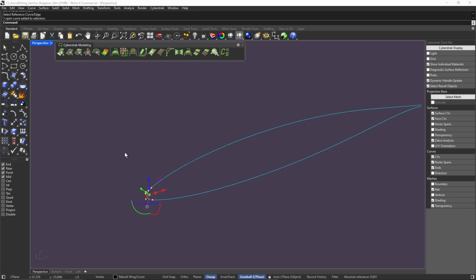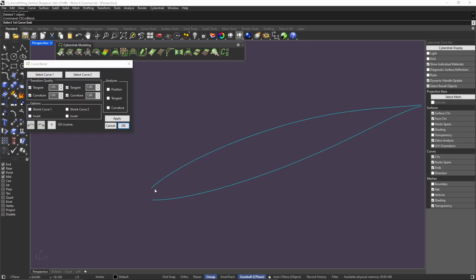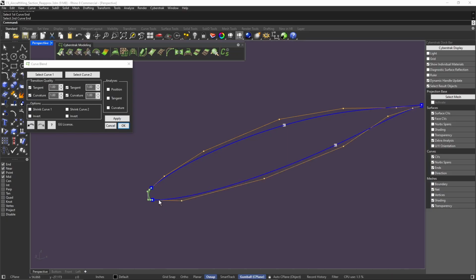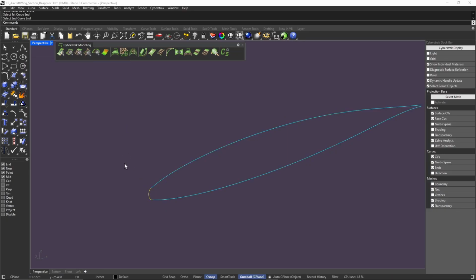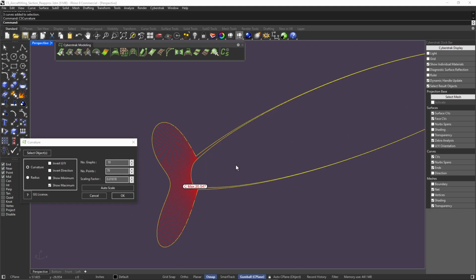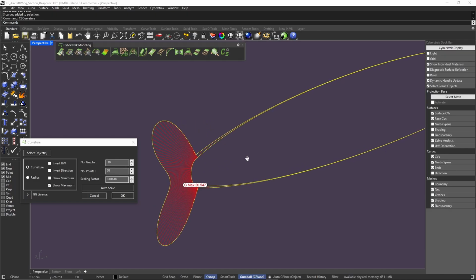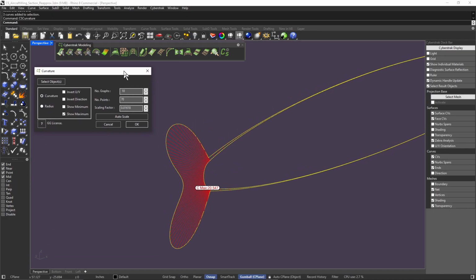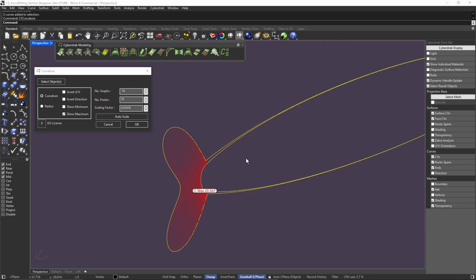And now we are going to delete the existing curve here, and we are going to rebuild that one using the blend curve command. Right mouse button click. And if we now look at the current result, obviously this is not better. It's actually worse than what we had before, but its curvature continues, and from here we can work our way to a better curvature distribution.